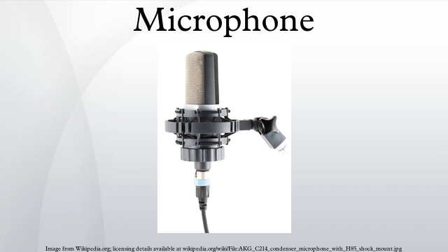RF condenser microphones use a comparatively low RF voltage, generated by a low-noise oscillator. The signal from the oscillator may either be amplitude modulated by the capacitance changes produced by the sound waves moving the capsule diaphragm, or the capsule may be part of a resonant circuit that modulates the frequency of the oscillator signal. Demodulation yields a low-noise audio frequency signal with a very low source impedance. The absence of a high bias voltage permits the use of a diaphragm with looser tension, which may be used to achieve wider frequency response due to higher compliance.